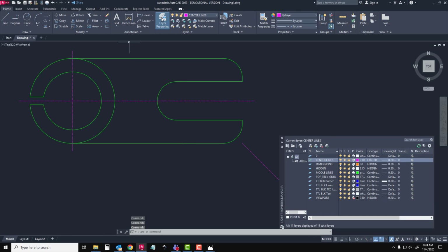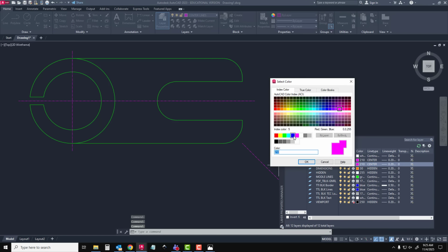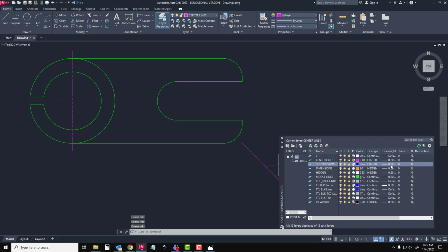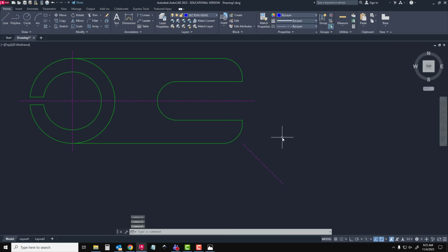Now, I'm going to make another layer. I'm going to call it section views. And I'm going to go with a very dark color, so blue, and this is going to be helpful because we're going to use this later. And I don't need any line weight to it. I'll go ahead and put a 3 on it just so you get an idea what it looks like. But what I'm going to do is double click on section views, and I'm going to make a line, and I'm going to go right through. Notice how I've got this going on right here. I'm going to hit F8 because I want it to be straight through, and then I'll just simply click it and I'll hit escape. Now notice this came in as a center line, so I didn't like that.